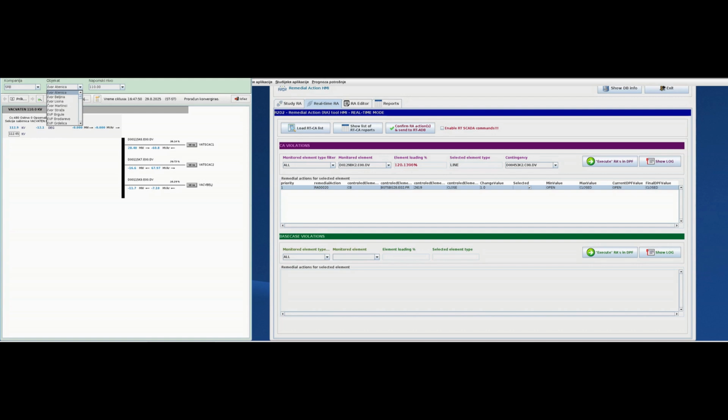So the dispatchers are now choosing the substations Belgrade 20 and Belgrade 28 in the report of the analysis to see if there is some possible overload. The line between Belgrade 28 and Belgrade 20 is connected and is loaded around 70%. So that is the expected load, and there are no other overloads of any element.